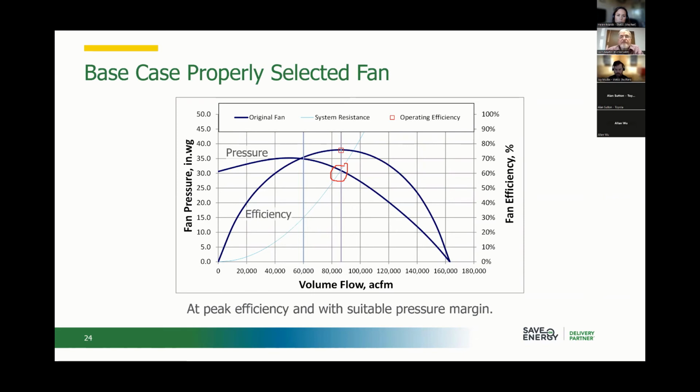So you might have a fan that's at 75, or you might have a fan that gives you the same flow pressure relationship, but the efficiency is higher. Or you could have one that's lower. I'm going to show you two different fans here. This is what we call a backward inclined fan. These blades are actually curved. If this was a big industrial fan, you'd look at that one and you'd go, yeah, they could probably hit 85% efficient with that fan.